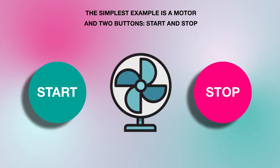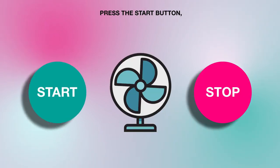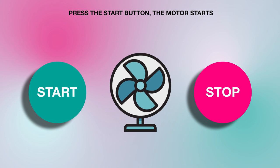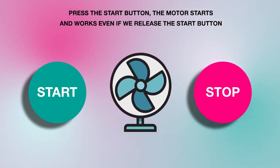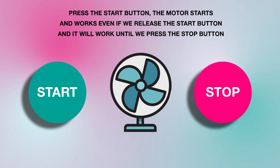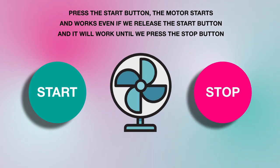The simplest example is a motor and two buttons, start and stop. Press the start button. The motor starts and works even if we release the start button. And it will work until we press the stop button.